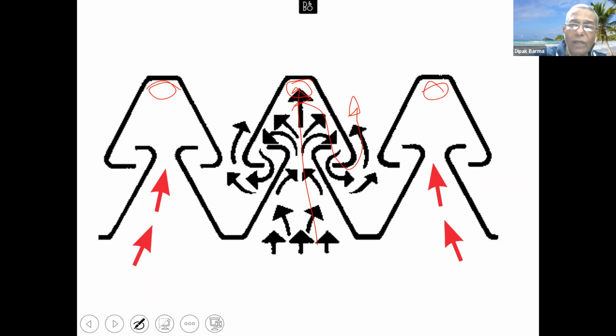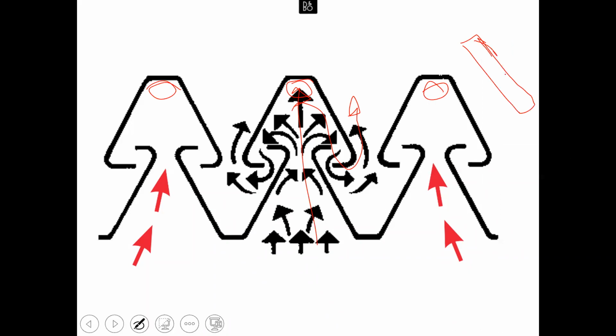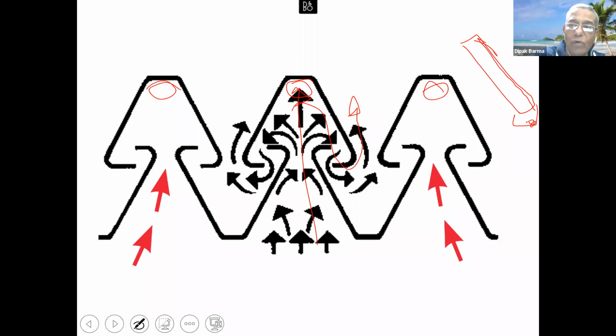When you have the filter at an angle like this, the grease is collected at the last point here, starts draining out, and you have a drain pan to remove the grease from there. So none of the grease falls back into your food being cooked. That is the reason why these baffle filters are very important and are used regularly along with the hoods.